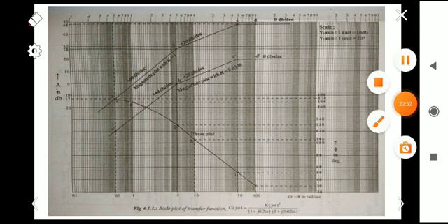We plot the 4 points, and after that we draw the line. So this is the actual magnitude plot we have to obtain. The first one is the magnitude plot corresponding to k equal to 1, but we are asked to find the k corresponding to the gain crossover frequency 5.